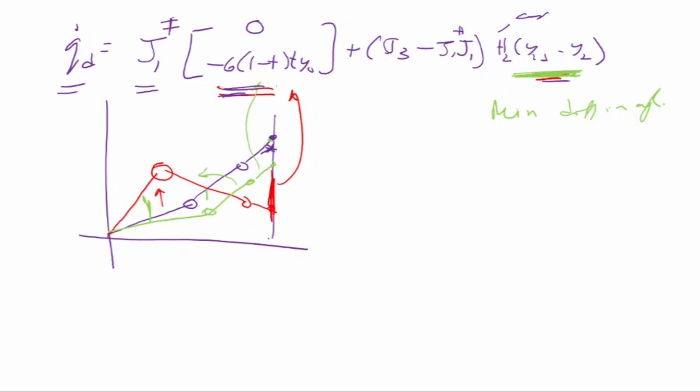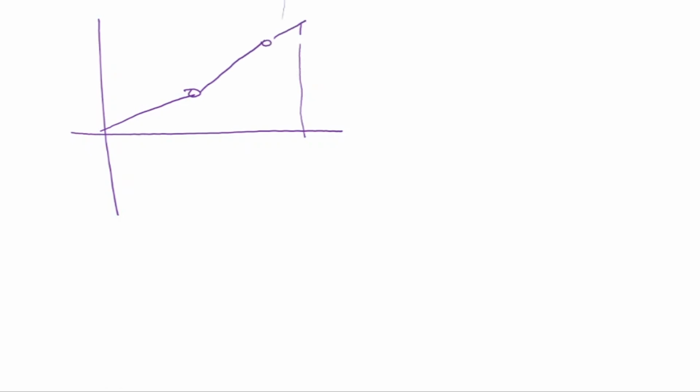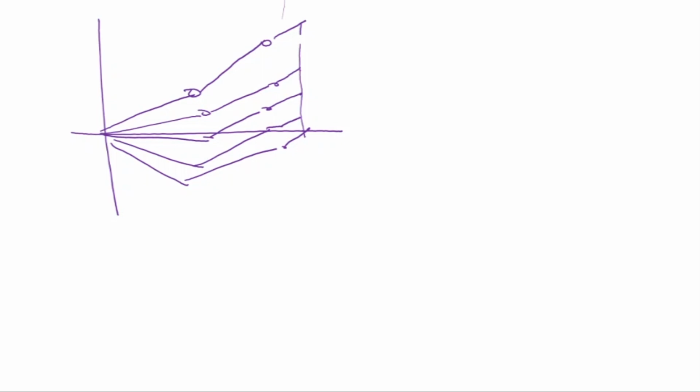So this is one solution that I'm getting. And then whatever solution I have got, I'm taking the difference in the angles between the constraint that I have to try to keep near to and the present solution, and trying to minimize that. Okay, so what we are getting is, if I do the inverse kinematics this way, this was my initial position, and if you're just coming down like that, it is going to come down like this. The manipulator is just coming down. It has followed the straight line, but without a constraint.